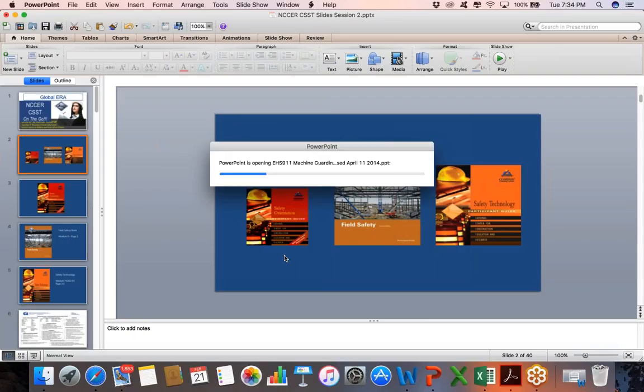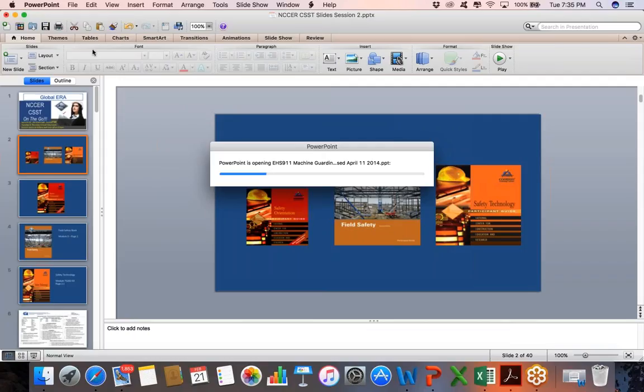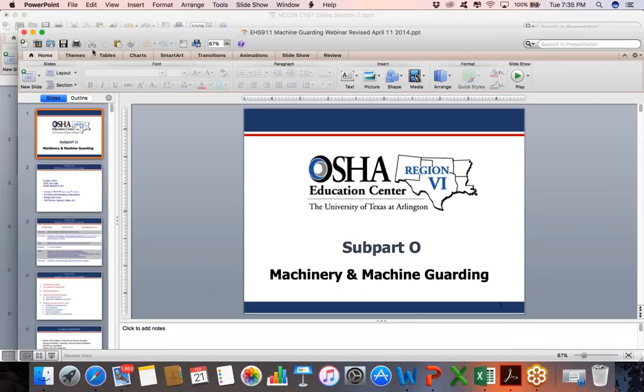Also, interlocking safety gates. What are we talking about? Gates to where if they're open, the machine will stop, right? The piece of equipment will wind up stopping. That's a perfect example. Also, hand switches, any type of switches located outside the danger zone that have to be touched or held for employees to do the work. I'll show you what I'm talking about on that one.